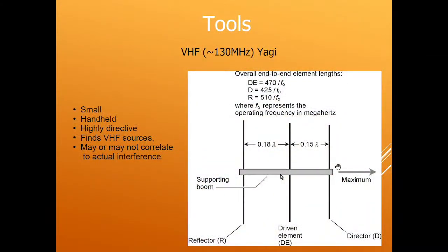So one other tool that I didn't describe in the talk, and I didn't bring one with me, is an acoustic device. It's a parabolic microphone, and you can point this at a power pole, and you can actually hear the arcing acoustically, and it's very directive. So with that kind of a device, you could probably get it down to which insulator it is at the top of the pole.